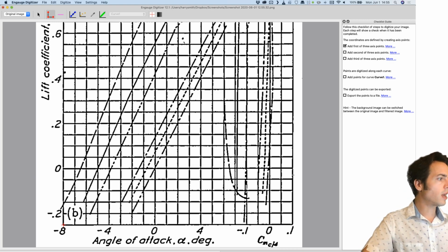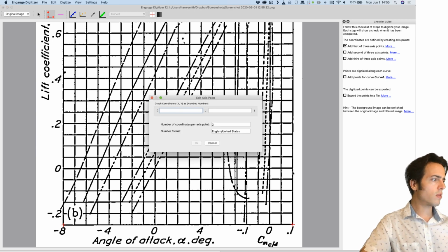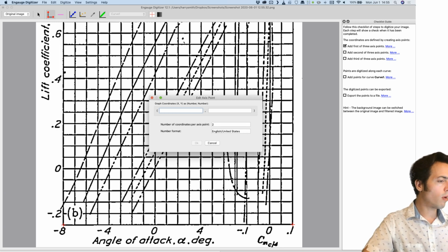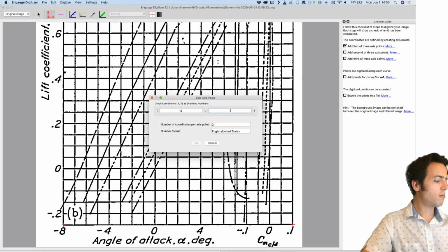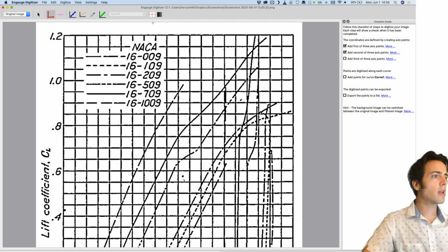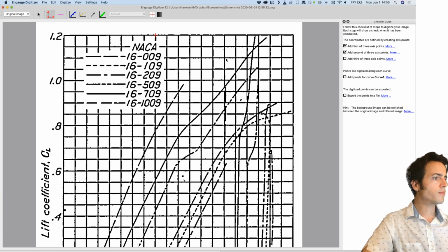Then I'm going to pick another one. Let's pick over in the bottom right hand side. The x ordinate is, well, let's be very careful here because there's 2 graphs being shown. We want the angle of attack, so it's going to be -8, -4, 0, 4, +8, that's going to be +12 there. So it'll be +12, and the y will again be -0.25. And let's just choose up here, let's say this line here, this was 0 and 1.2.